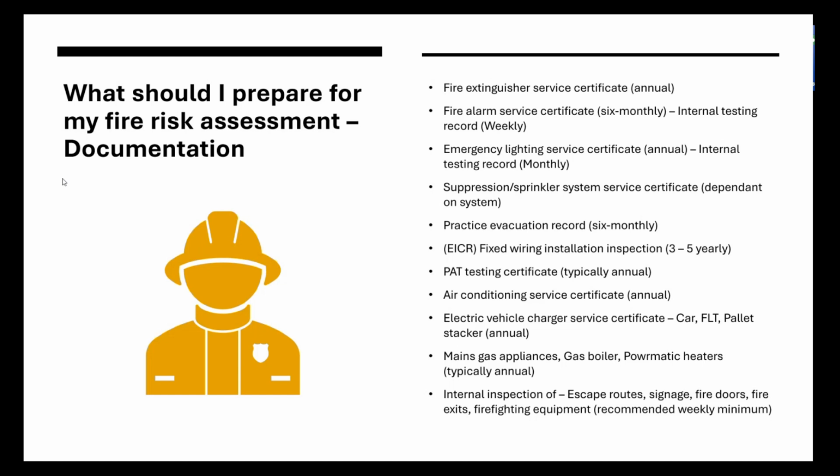So your emergency lighting service certificate, which is on an annual basis, would be done by an external competent electrician or fire safety technician, recommended to be done by those. I have some people that try to do it themselves internally. Are they competent to do so? I would say no. Maybe you can test the emergency lighting, maybe you can do the 3-hour discharge test on it. However, you are not competent to identify electrical faults, and you are not competent to rectify these faults. So it's better to just use a competent person in that one.